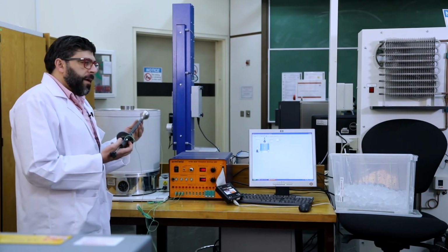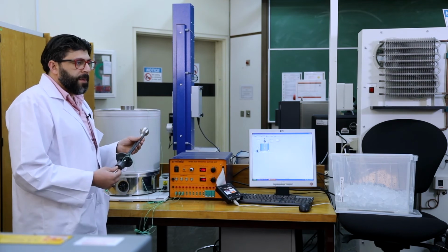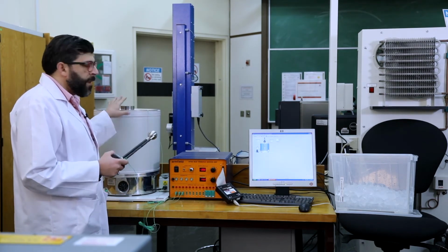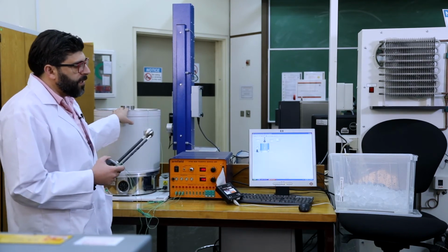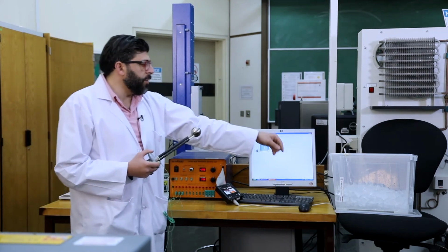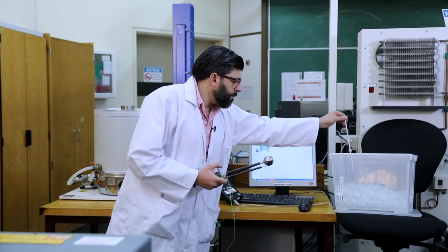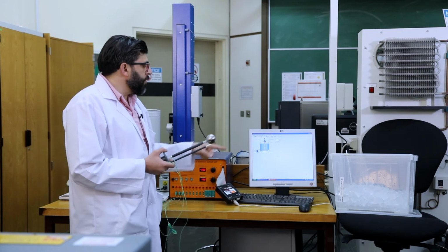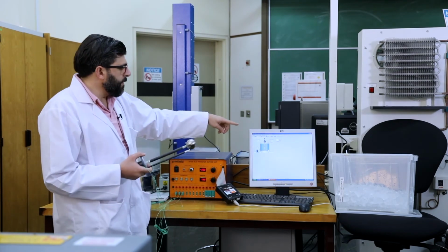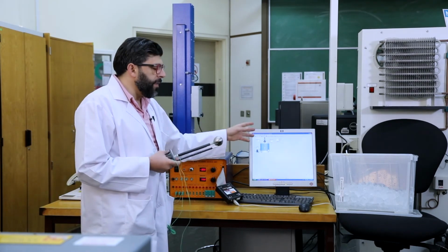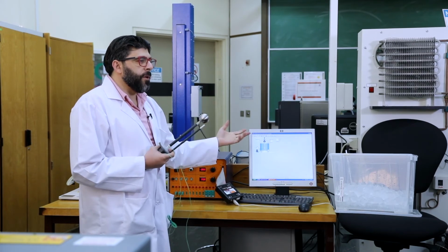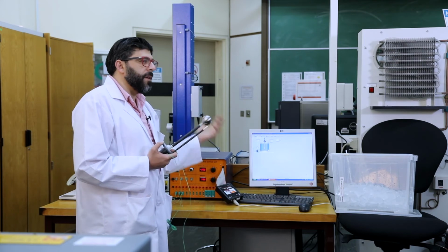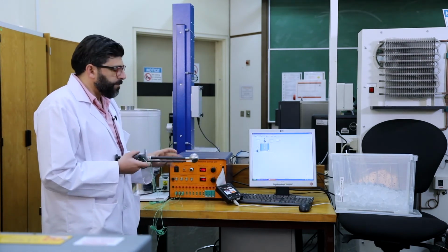So that will be my first experiment. And then we'll repeat the experiment again, but in the case of cooling. We'll take it out of the bath water and put it here in the ice box. In this ice box, we check the temperature to ensure that it is correct. Then we will measure again the change in temperature for cooling, and then we can check the Biot number, and if the Biot number is 0.1 or less, then we can apply the lumped model.